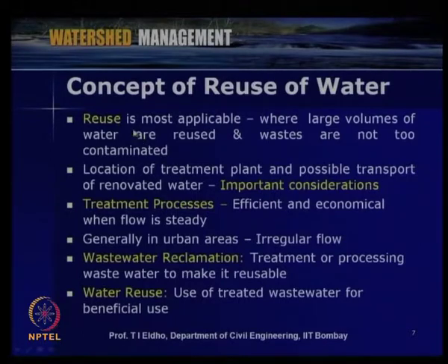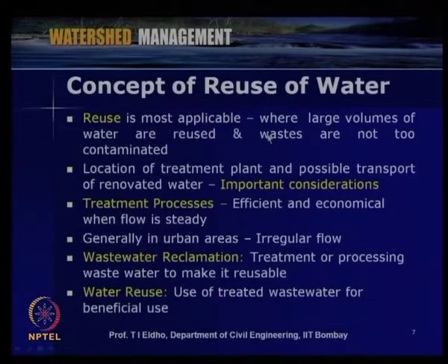As we are discussing, reuse is most applicable where large volumes of water are reused and the wastewater is not too contaminated. For example, the water coming from cooling processes is not much contaminated, so we can directly reuse it. Or the contamination in the water is much less, say after washing or some of the processes, then reuse is most applicable.